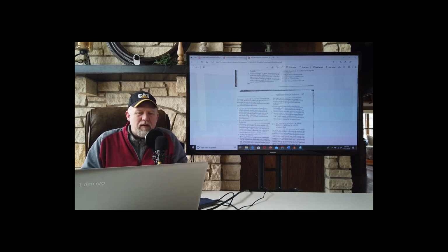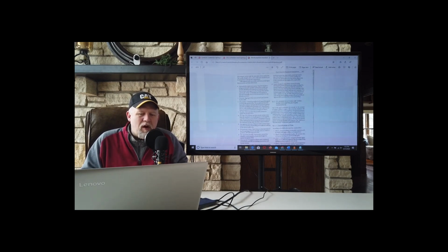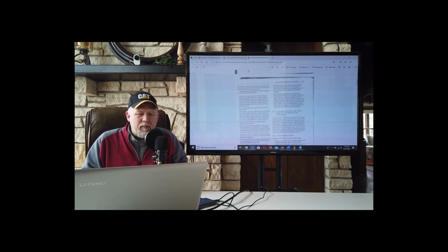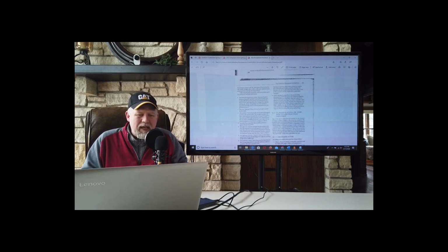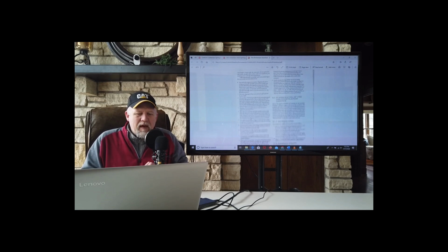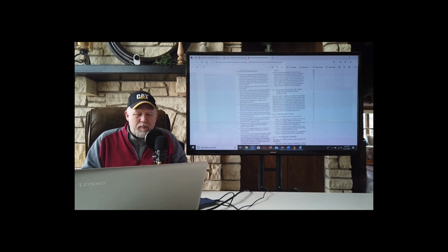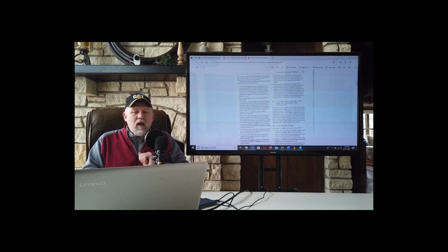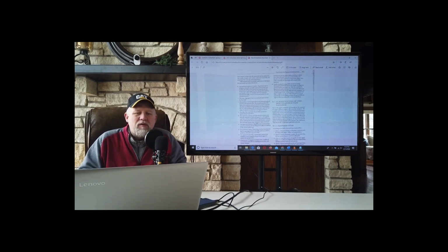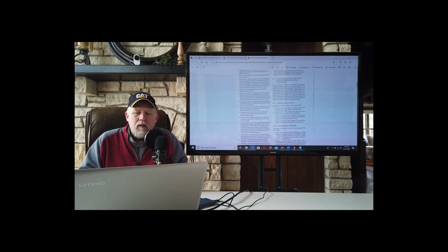Know some of the terms here on page 267. Read through all of them, but knowing some of them is very important. Like, what's the difference between a fire separation boundary or a fire separation assembly, fire protection rating, fire separation distance? What is a fire wall, a fire door, fire partition, and a fire area? Those are all things you're going to come across again and again and again in your career. So look through those. Those are incredibly important. Right?